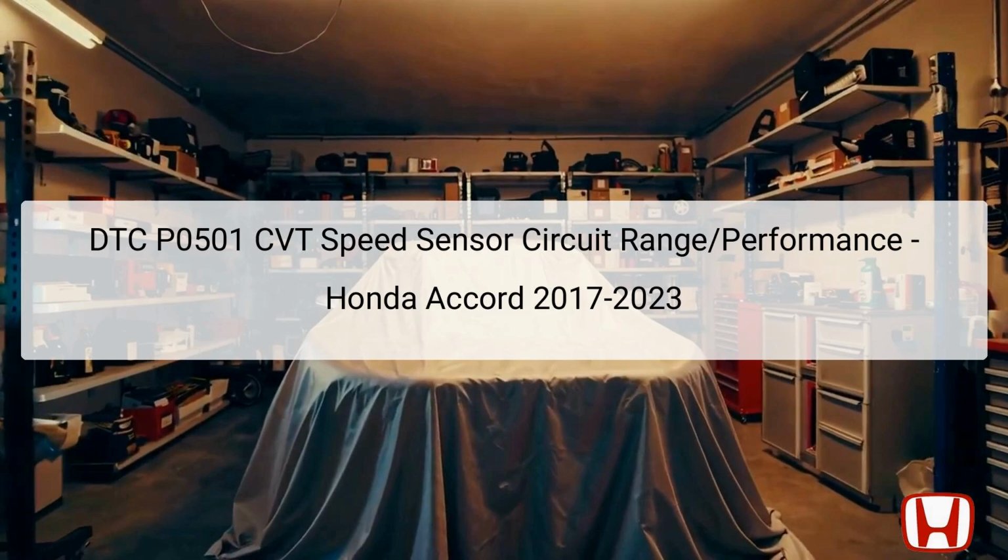DTC P0501 indicates an issue with the continuous variable transmission CVT speed sensor circuit, specifically relating to its range or performance. This error affects the CVT speed sensor and the transmission control module, TCM, both crucial for the accurate reading of the vehicle's speed and smooth operation of the transmission. The CVT speed sensor is located in the transmission assembly, where it measures the rotational speed of the transmission. This data is sent to the TCM to ensure optimal performance and fuel efficiency.